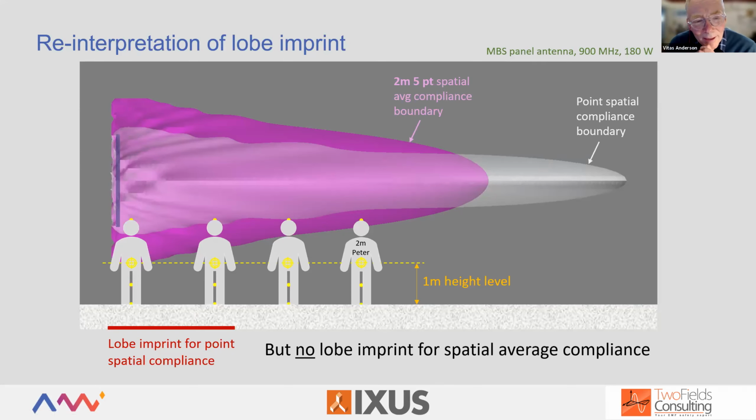And so Brendan's idea was that, rather than focusing so much on showing compliance zones from the antenna, in a way it's actually more useful just to show the lobe imprints on the ground, because they're easier to interpret for people wandering around the rooftop, so long as they're not climbing up an antenna where they might pop into a compliance zone of an antenna overhead. So anyway, something to think about there.